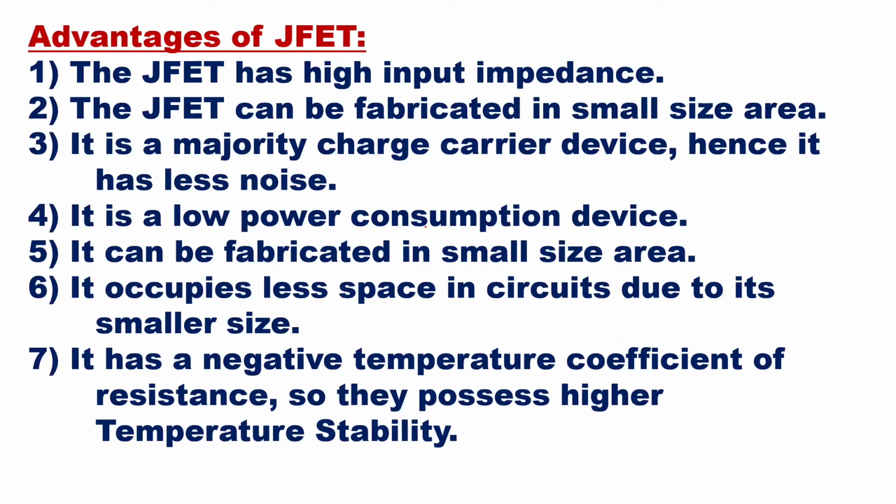Then we'll see what are the advantages of JFET. The JFET has high input impedance because the input that you are going to apply at the gate terminal, you are going to reverse bias it, so it will be having a high input impedance. The JFET can be fabricated in small size area. It is a majority charge carrier device, hence it has less noise. It is a low power consumption device, which is very important. It occupies less space in circuits due to its smaller size. It has a negative temperature coefficient of resistance, so they possess higher temperature stability.